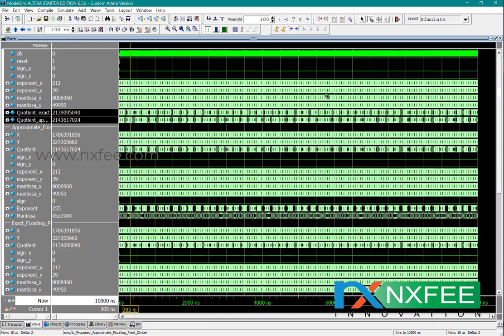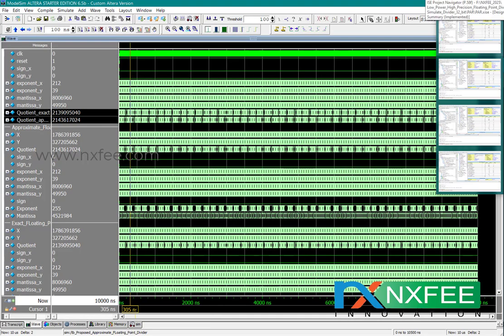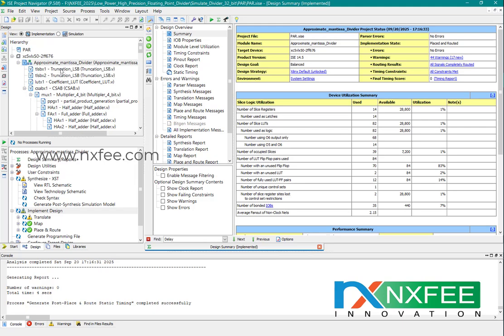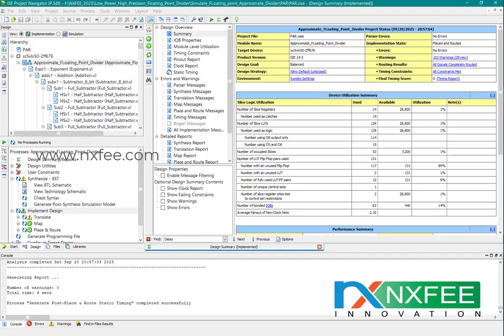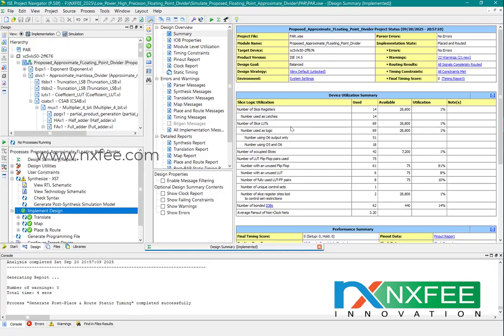Okay, then we synthesized this code in Xilinx Virtex-5 FPGA. Here this is the division code for the existing system, and this one is the proposed design. This one is for the floating point division operation of the existing code. It takes 129 LUTs, but the proposed one occupies only 69 LUTs. Slice register is equal to 14, occupied slices equal to 42, and IOB equal to 62.